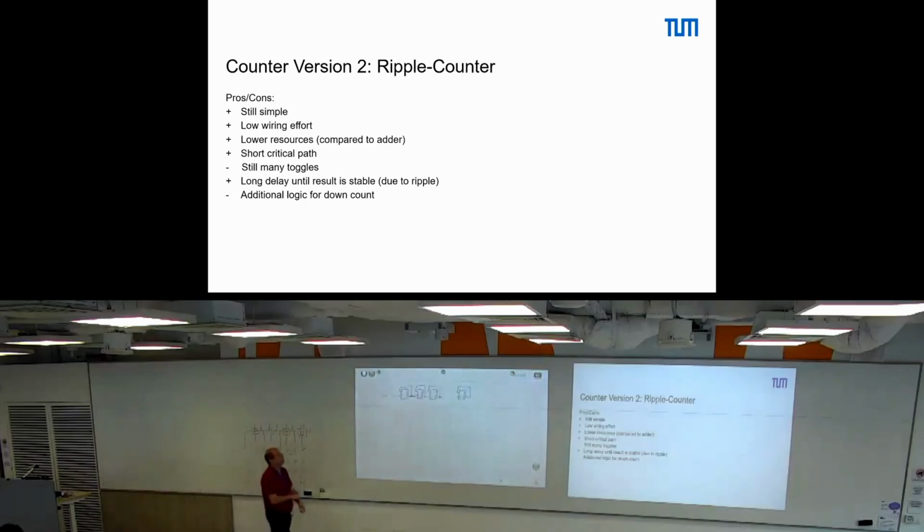if we have a rising edge here at the input and we initialize our circuit with all 0, so we have here some reset or init signal that resets our circuit to 0. Then with the first rising edge, the value of Q bar, which is 1, goes to 0. Yeah? So the internal state is 0, 0, 0, 1.